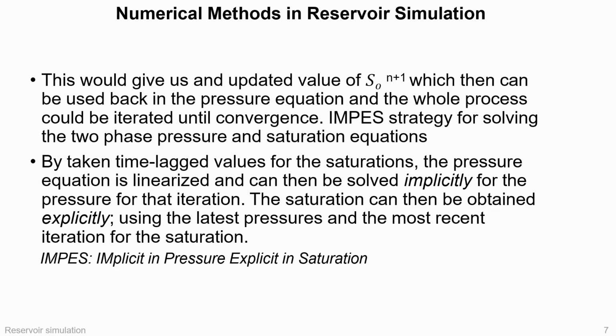Implicit pressure calculation can handle larger time steps more robustly, while explicit saturation updates reduce complexity. However, explicit saturation treatment may require smaller time steps to remain stable. So IMPES is a good example of a practical engineering compromise in numerical simulation.